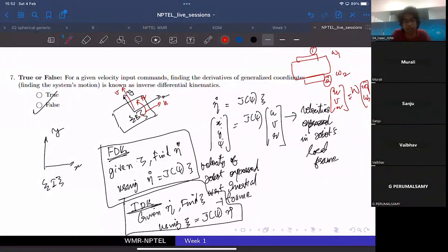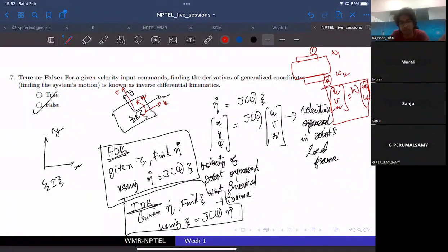You will have some configuration matrices, and it will depend on the configuration of the robot. This you will see in the upcoming weeks. But as of now, UVR is the instantaneous velocity of the robot expressed about its own local frame of reference. In the upcoming week, you will find a mapping between UVR and omega-1 and omega-2. If the robot has four wheels, you will have four omegas. So further transformation you would see in upcoming weeks. Thank you. Okay, thank you.